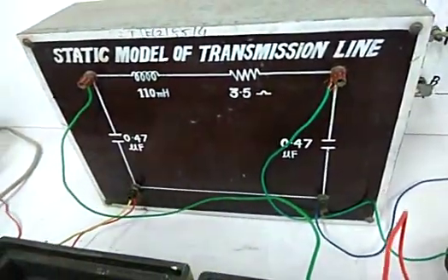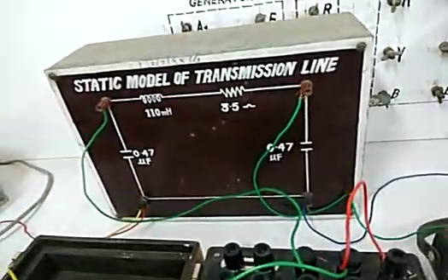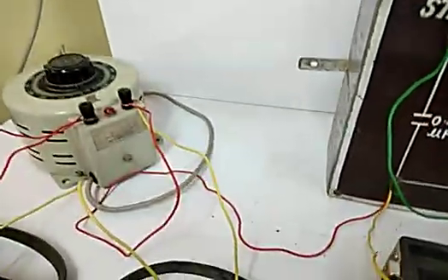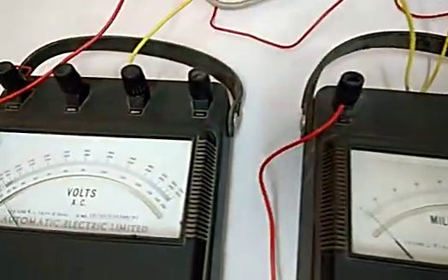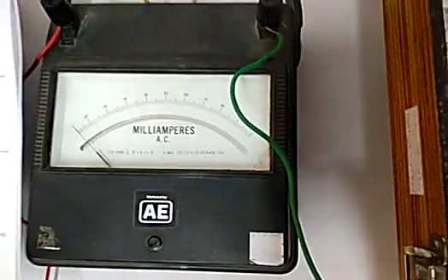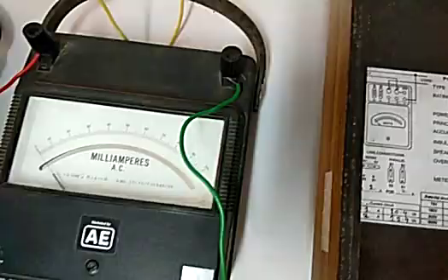Now if you see the circuit diagram, accordingly I will explain the connections for the open circuit test first. So we are giving the supply through the dimmerstat. From the auto transformer, the connection is going to the ammeter, this red color wire. Then from the ammeter, this green color wire goes to wattmeter M.